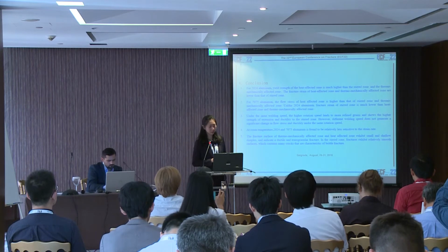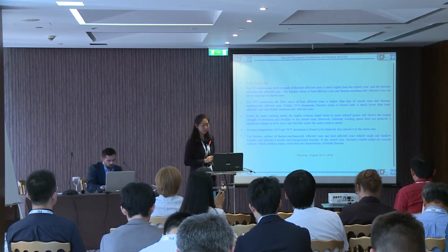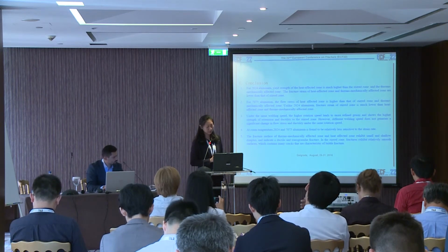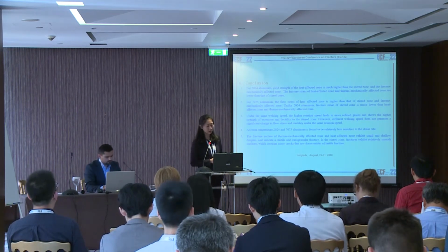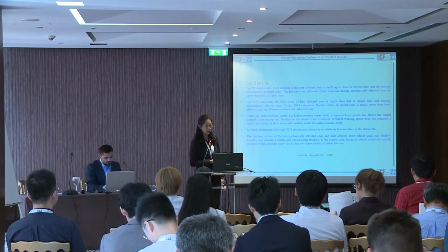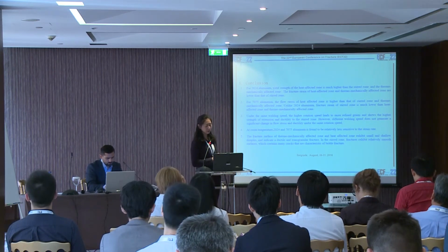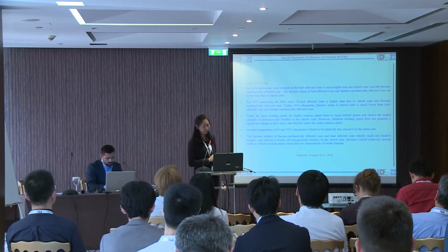And under the same welding speed, the higher rotation speed leads to more refined grains, and shows the higher strength and ductility in the stir zone. But the different welding speed does not generate a significant change in flow stress and ductility.